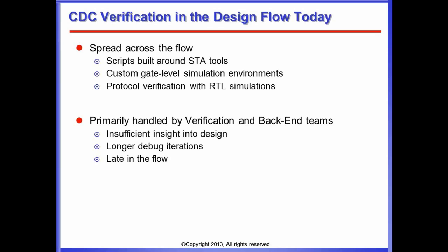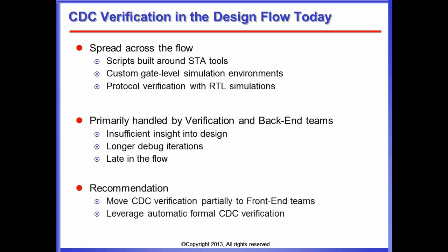So it's a fix late in the flow, and as always, fixing something later in the flow is more expensive in any term. So what we recommend is to move to a dedicated CDC verification tool, and also automate the verification of the CDCs, as there's this rule that the front-end designer shouldn't verify his own block with his own parameters and test bench, right? By automating that, you can move the verification of the CDC to the front end and get a more error-free, more robust design in the back end.